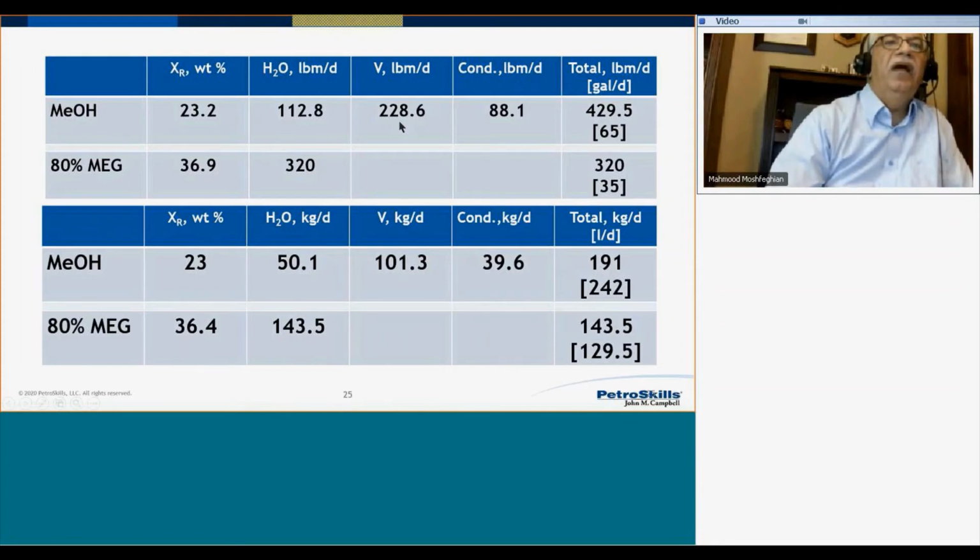And in addition, the gas may end up in a molecular sieve dehydration. And again, methanol is a poison or degrades the molecular sieve 4A and loses its effectiveness, causing operational problems. So clients hate to have methanol in the vapor phase.